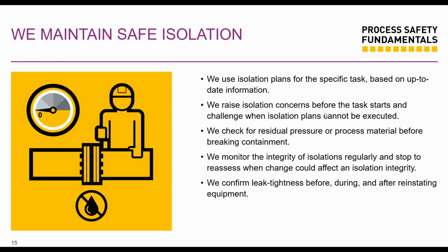We are to raise isolation concerns before the task starts. So you want to work on a pump, and stuff is still operating, or we have other equipment still operating, even if that pump is off. We want to challenge the isolation plan. Do we have our double block and bleeds in place? Are we blind flanging it? And our isolation valves, are they holding? We want to go there and make sure that we can actually isolate.